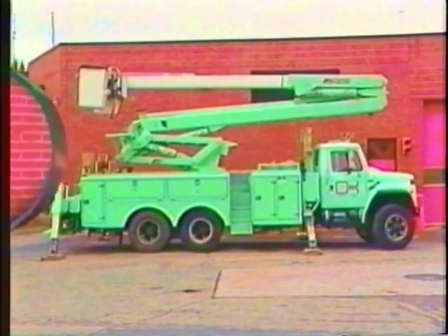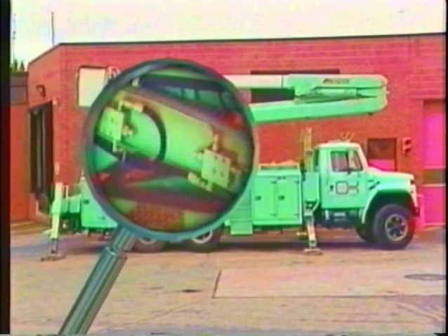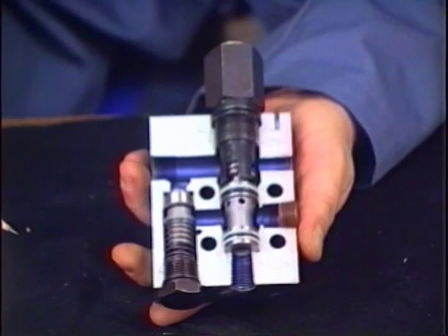Some other protective devices you should be aware of are the holding valves located on each of the hydraulic cylinders. In the event of system failure, the holding valves trap oil in the cylinders and prevent the affected systems from collapsing. You can think of a holding valve as a kind of one-way street, allowing fluid to flow in one direction only. Let's listen as our demonstrator describes the valve's operation.